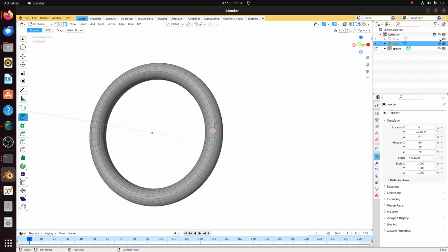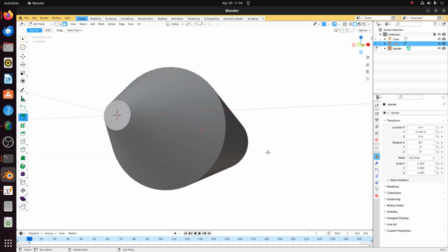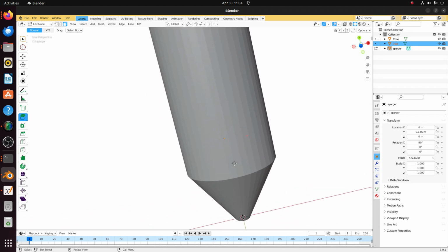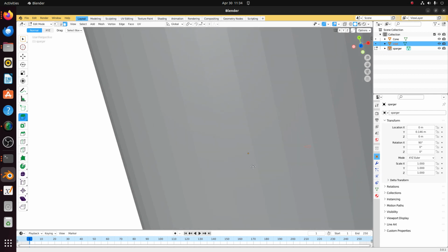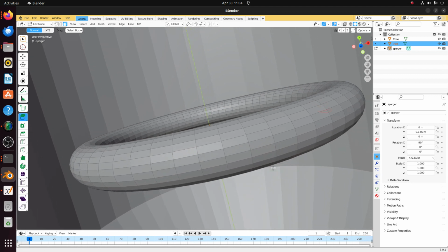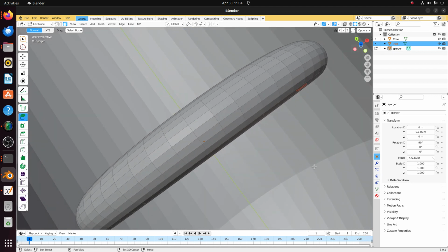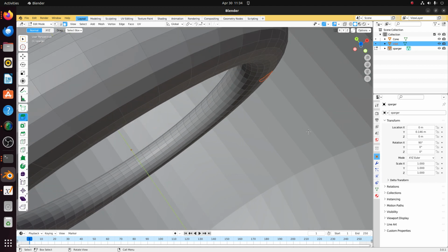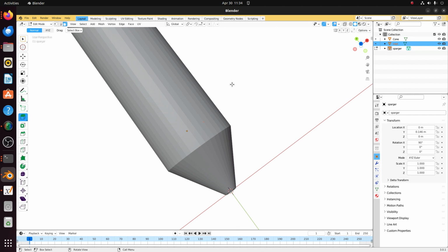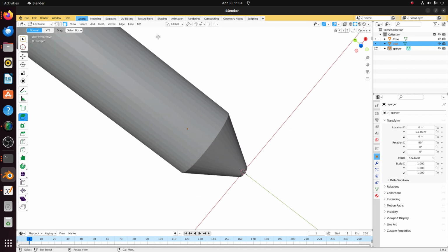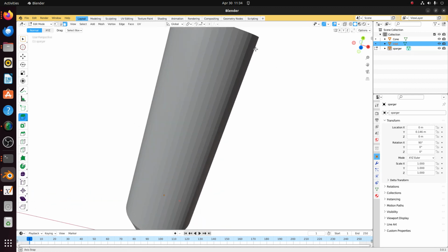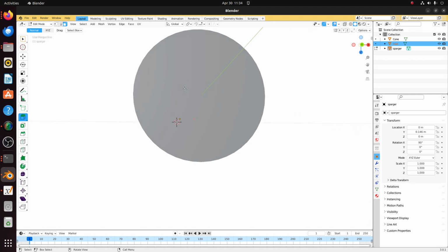And now viewing with the entire geometry, we can see that it is rightly placed. This is the inlet that I have constructed. These are the entire walls of the fluidized bed. And I also want to separate or make an outlet. So this will become the outlet of the system.